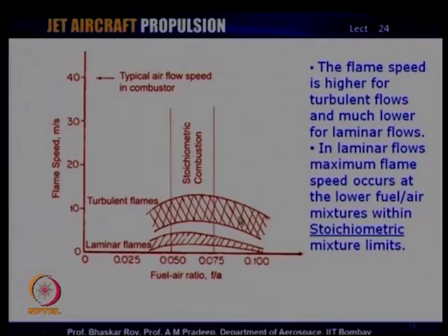If it is more, the combustion will get extinguished because of the richness of the fuel, and if it is less, it will become what is known as a lean combustion, and the combustion may get extinguished because of lack of fuel or too much air. So, too much fuel or too much air will result in extinction of the flame. So, you have to hold the flame within that stoichiometric ratio zone and still hold the air in a low velocity area.